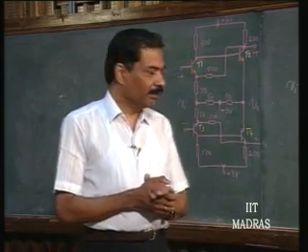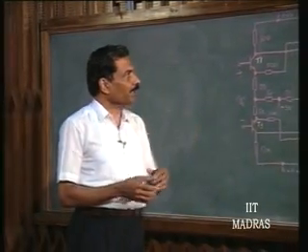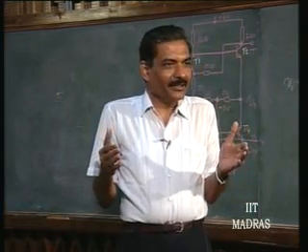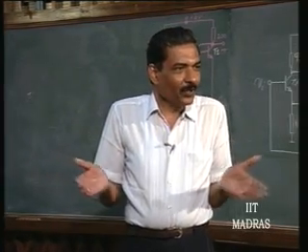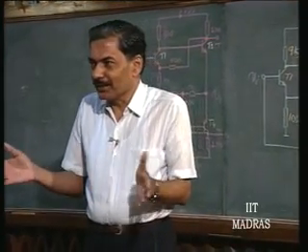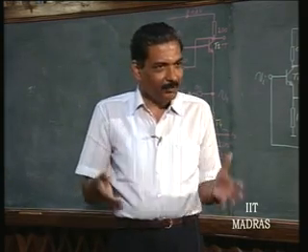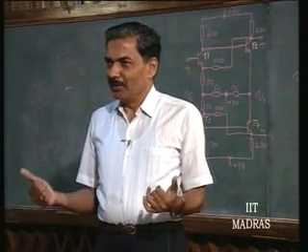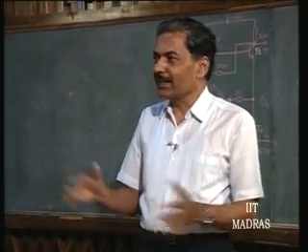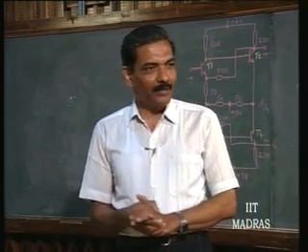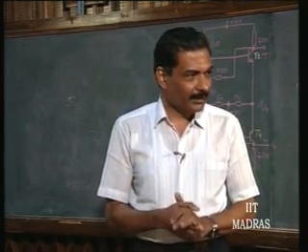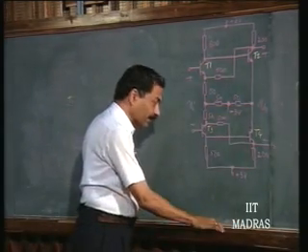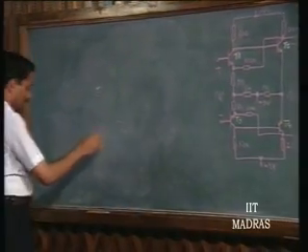earlier. And that is what is done in the case of one of the popular, this is the ultimate thing, that is nobody has yet gone for 4-stage cascaded for wideband configuration. At 3 stages they had faced enough complications to stop and say we are now satisfied with the what? Loop gain, okay, and also consequent desensitization of the amplifier parameters with respect to the active device parameters. Okay. So, this is the point at which design of IC wideband amplifiers had stopped, okay, and that is simply 3-stage configuration.